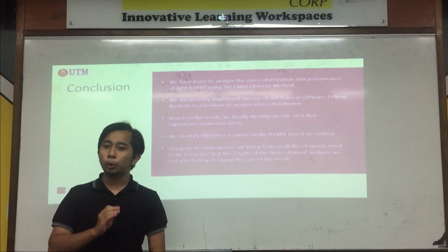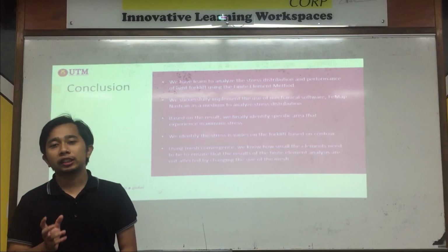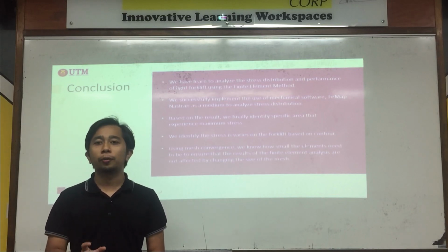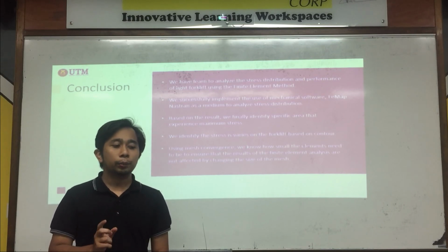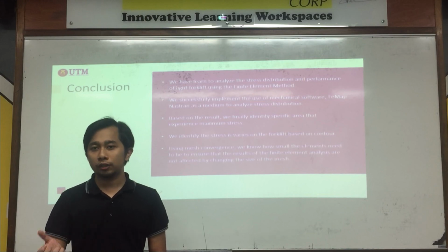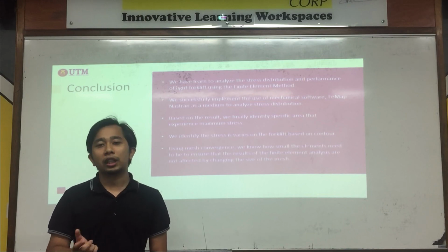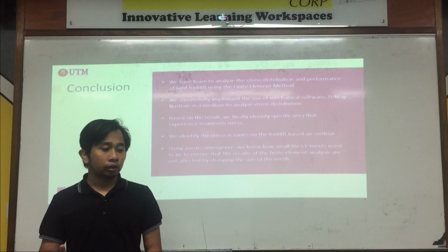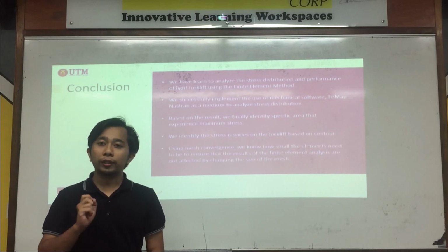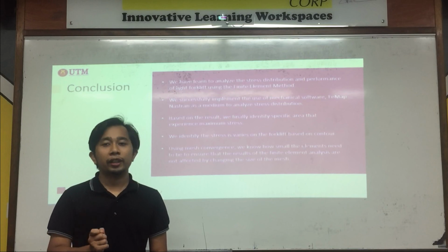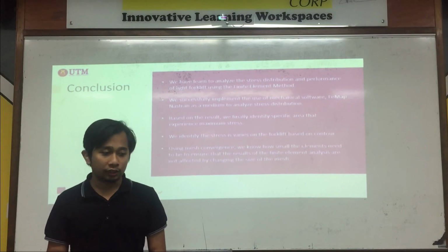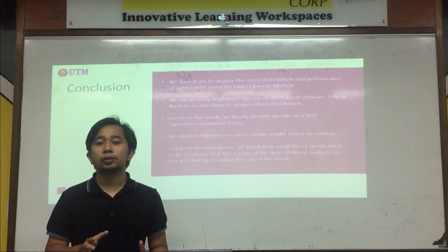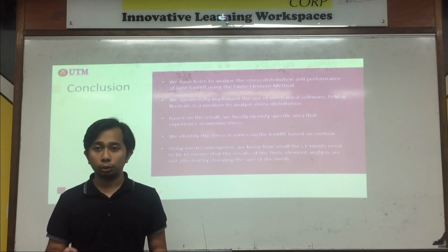For the conclusion, we have learned how to analyze the stress distribution and performance of the light forklift by using the finite element method, and we also successfully implemented the mechanical software such as the FeMap Nastran as a medium to analyze the stress distribution. And in addition, based on the result, we finally identify the specific area that experiences the maximum stress. And we also identify that the stress varies on the forklift based on the contour.